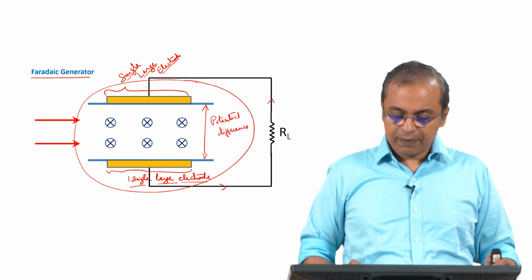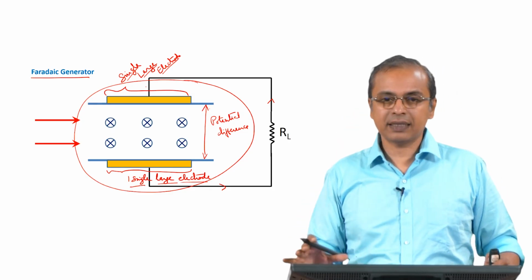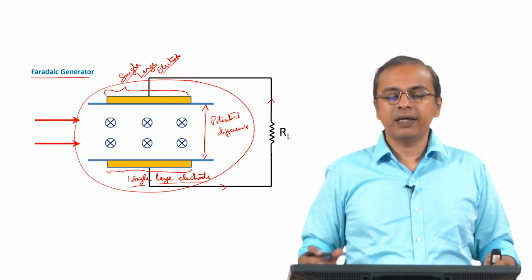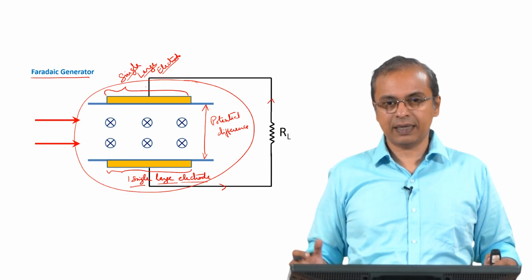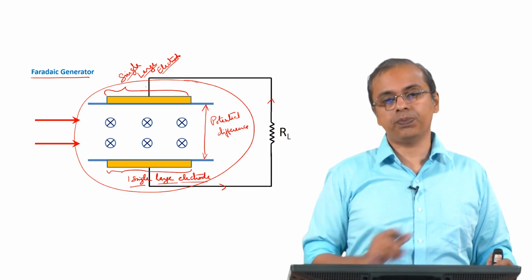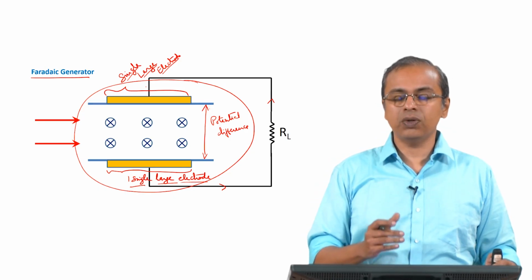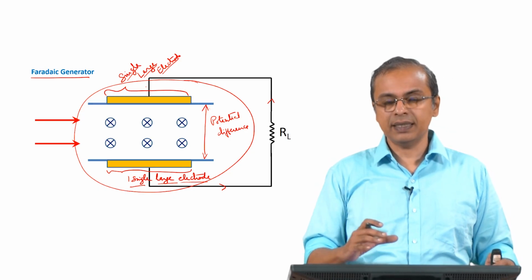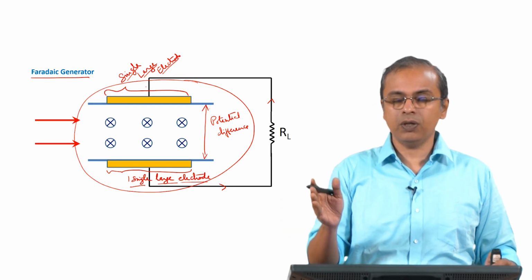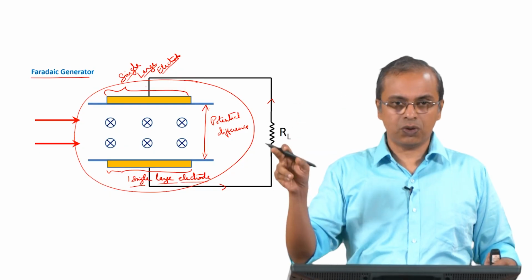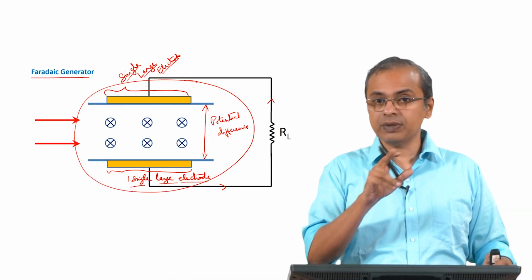Now even though you may be doing a Faradaic generator, by using a single large electrode and smearing out this Hall effect, you are actually not capturing as much of the energy, because you may have much better potential differences at various locations if you give the opportunity to pick up those potential differences. So instead of putting a single large electrode on either side of this region, we segment the electrode, so that you will now have a series of electrodes on top and a series of electrodes at the bottom, and you can pick them up as pairs. Now they are not in electrical contact.